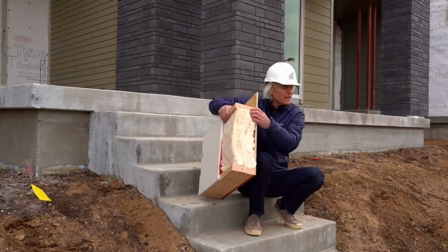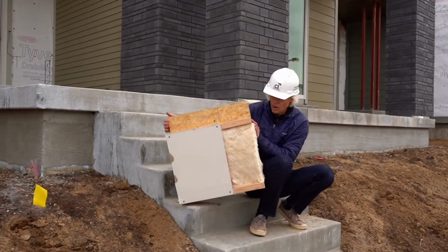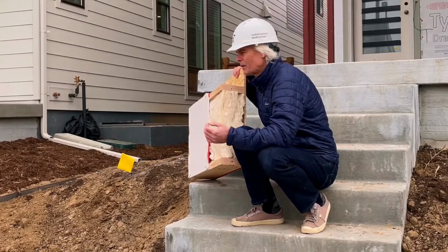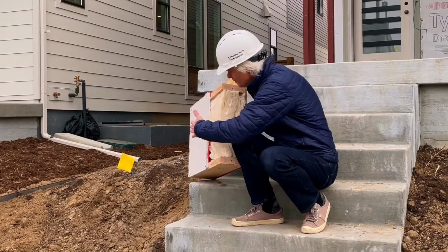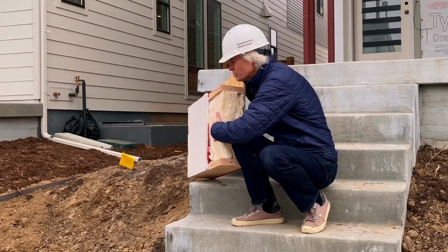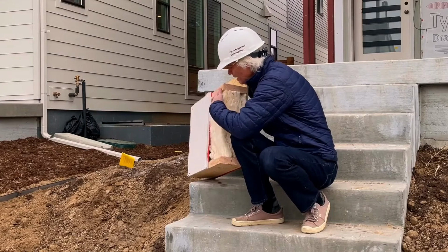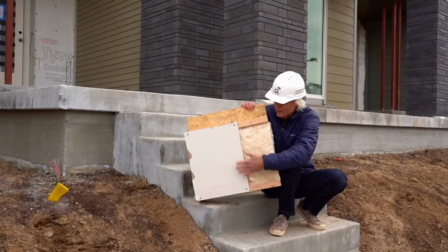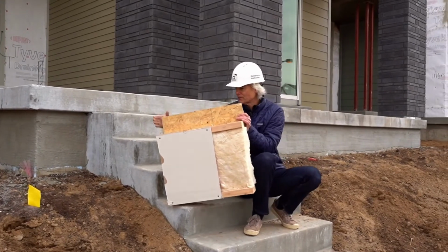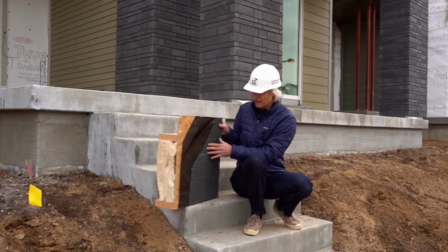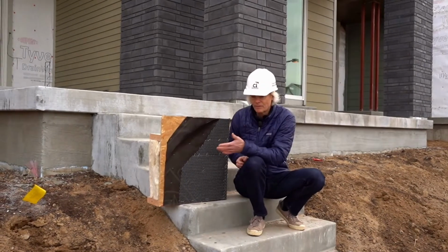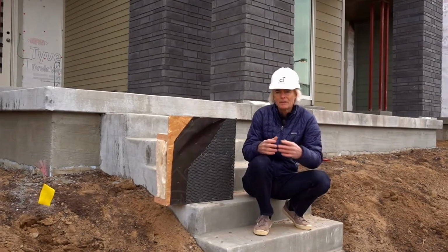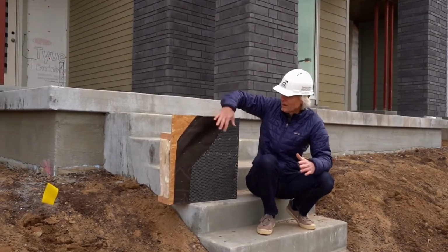What we typically see here is a 2x6 wall, and here we've just constructed a mock-up. We're in winter, so there's not a lot of active stucco projects going on right now today, but typically a 2x6 wall, R20 plus insulation cavity. Sometimes there's a vapor retarder, not typically in the Denver climate, and then wallboard, drywall on the interior side, but a fairly simplistic thing. We start to see the attachment of different staples to the lath, where you see abundance of staples, and so those are critical layers that we see here.